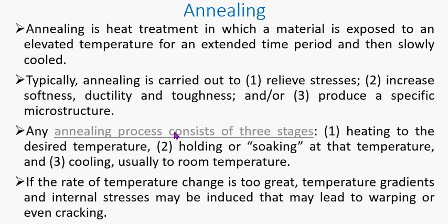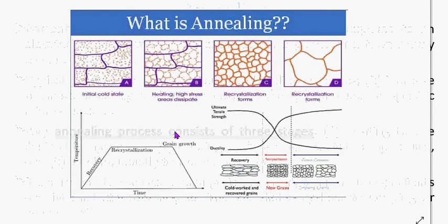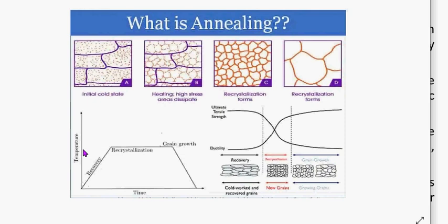So let's look at this diagram here. This is basically the summary of annealing. Here is the recovery stage, which is the heating stage. Here some physical properties can be recovered, such as thermal and electrical properties. Here is the relief of the stored strain energy from a much higher level to a lower energy state. But in this stage, mechanical property is not really altered.